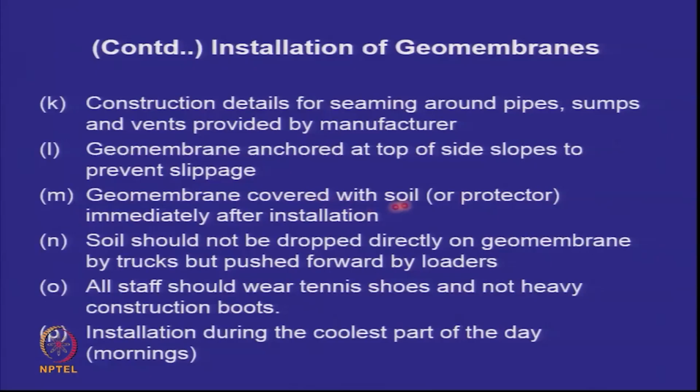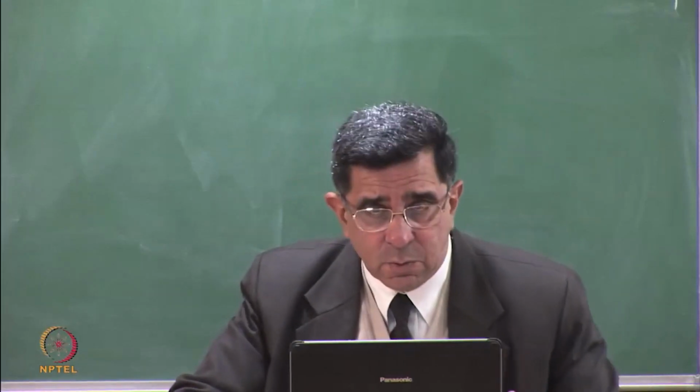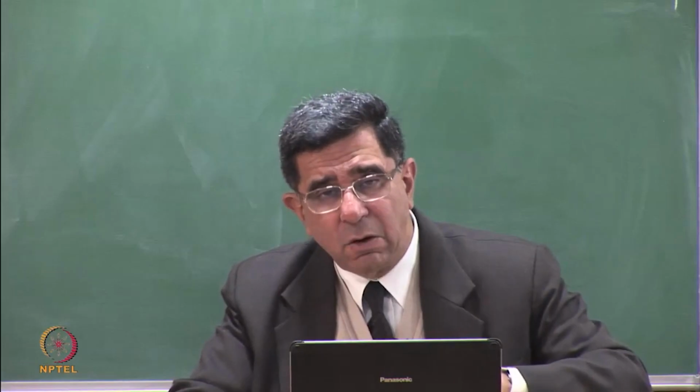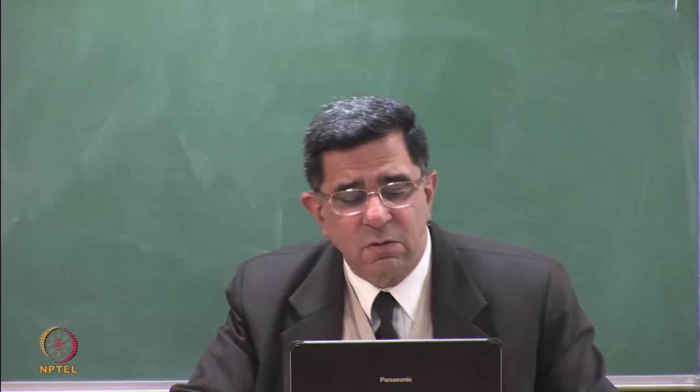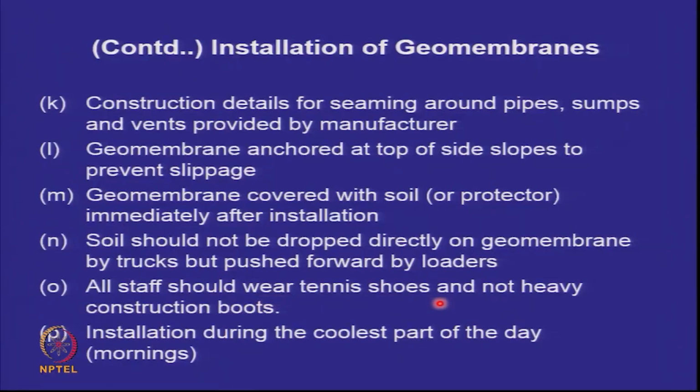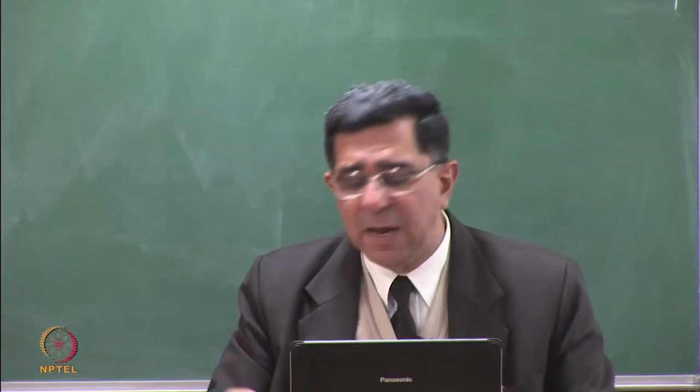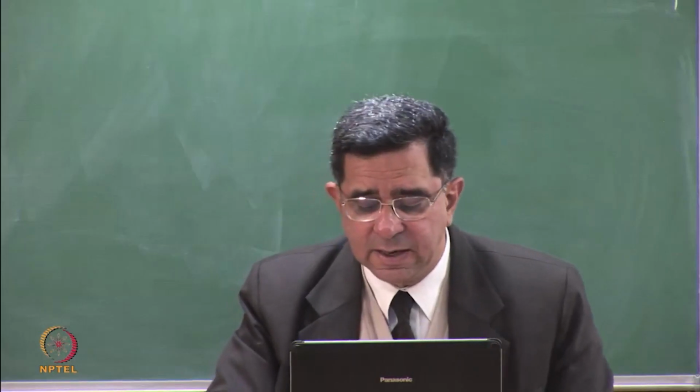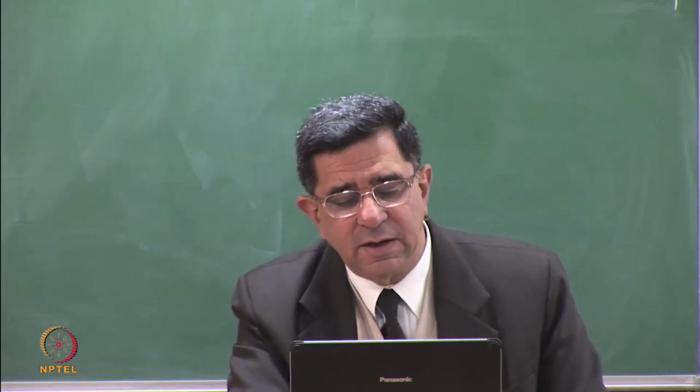Geomembrane should be covered with the soil or the protector immediately after installation. Soil should not be dropped directly onto the geomembrane but pushed forward. In India we do this manually, but in the developed world they use light crawler mounted loaders and they push this forward. All staff should wear tennis shoes and not heavy construction boots. Installation should be done during the coolest part of the day when the geomembrane has not expanded. Otherwise there is a thermal expansion coefficient of the geomembrane and they can become longer during the daytime.